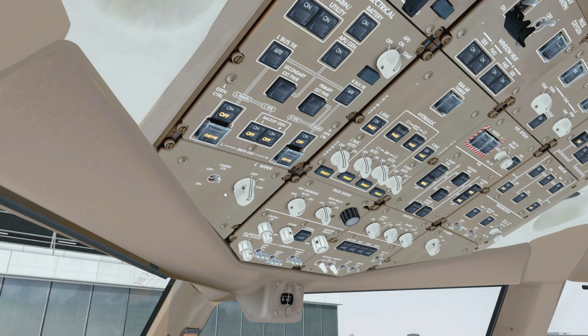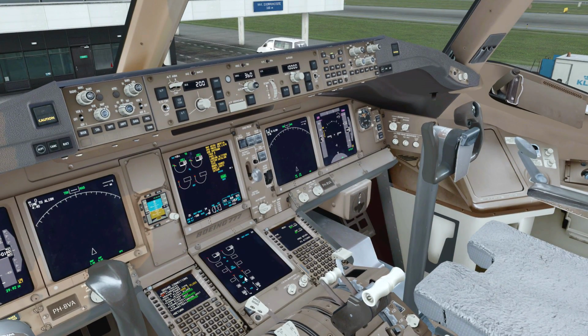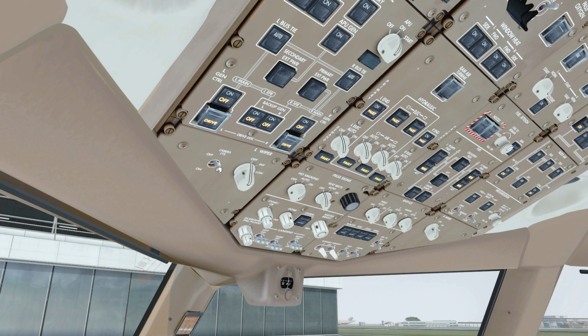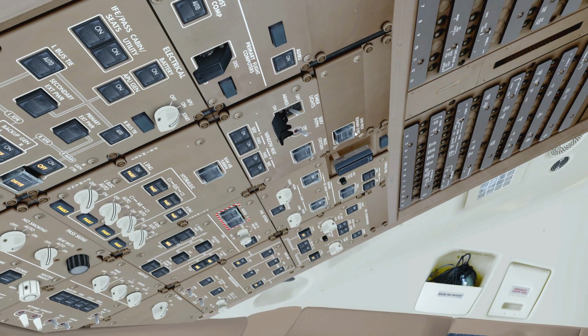Camera lights, this is used if you have that enabled. You have here on this display a camera view of the gear, so you can follow the taxi line exactly, and you can turn that on if you want to. In this case we don't need it. Wiper is also off. Then we can go to the next column, ground proximity runway override switch. We just leave that guard closed.